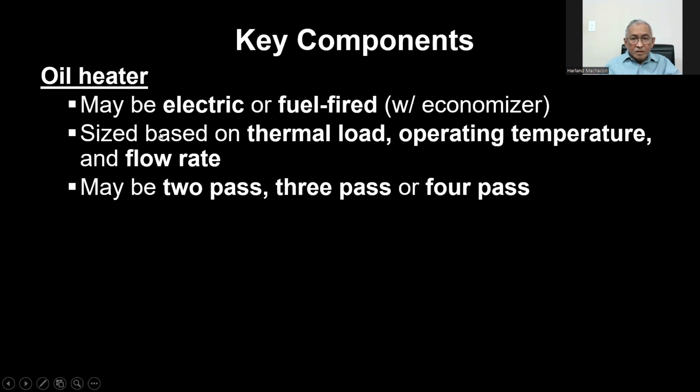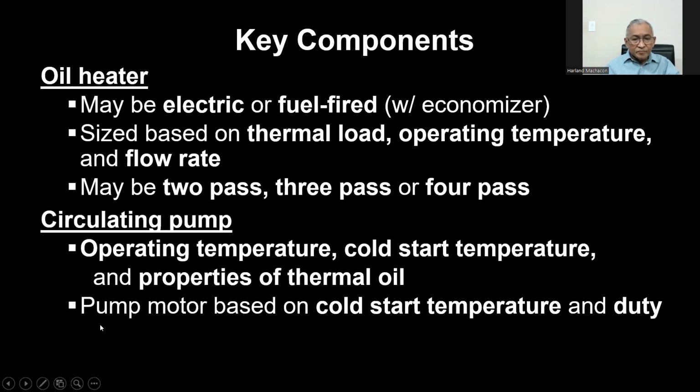What are the key components? Let's discuss it one by one. The first will be the oil heater. It may be electric or fuel-fired with an economizer to save on fuel usage. And it is sized based on the thermal load, the operating temperature, and the flow rate. It may be 2-pass, 3-pass, or 4-pass.